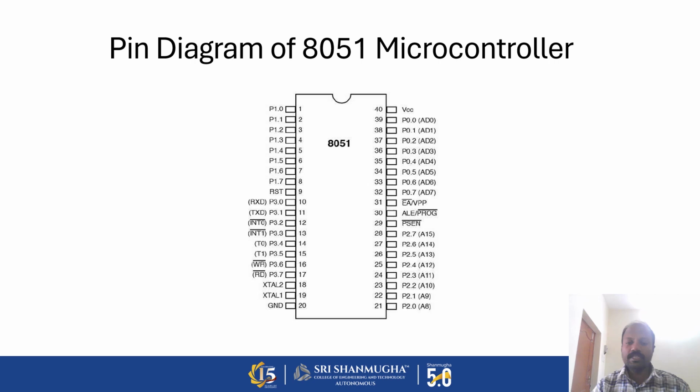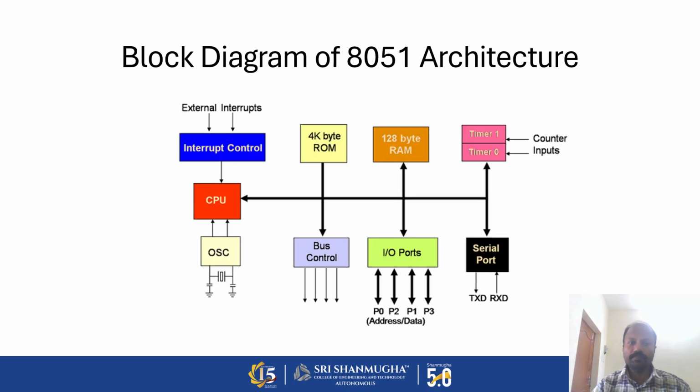And then we have PSEN, that is program store enable, followed by ALE, that is address latch enable, and then external access EA, followed by port 0, that is 8 pins of port 0, up to the 39th pin, and then we have the supply pin, VCC, at pin number 40. So this is the pin diagram of the 8051 microcontroller.